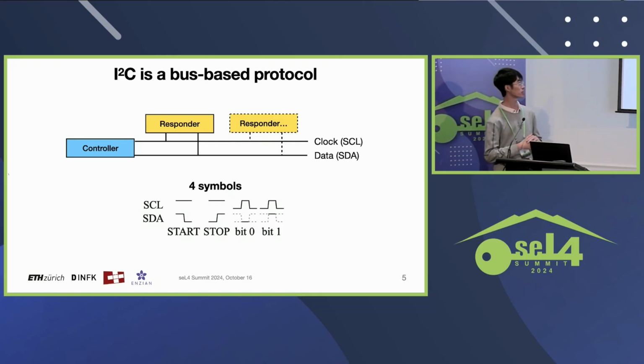On an I2C bus, there's one controller and one or more responders. In a BMC, the controller is the BMC itself, and the responders are those power regulators, temperature sensors, and so on. It is always the controller that drives the clock line, with some exceptions. And depending on the transaction type, either the controller or the responder drives the data line. So on those two wires, the electrical signal encodes these four symbols.